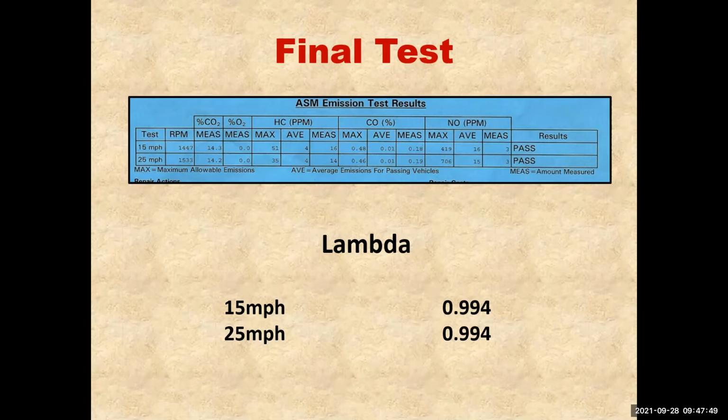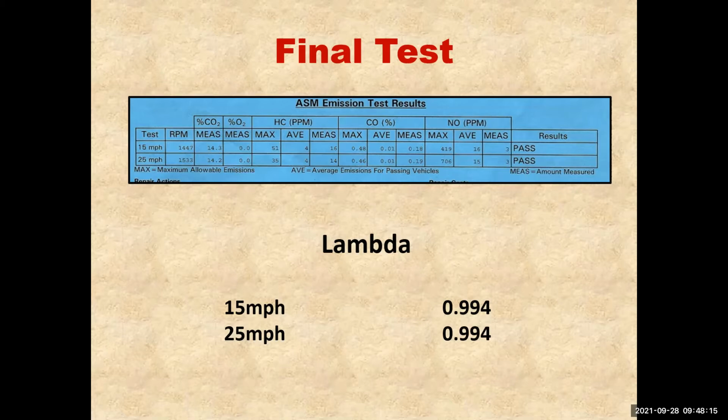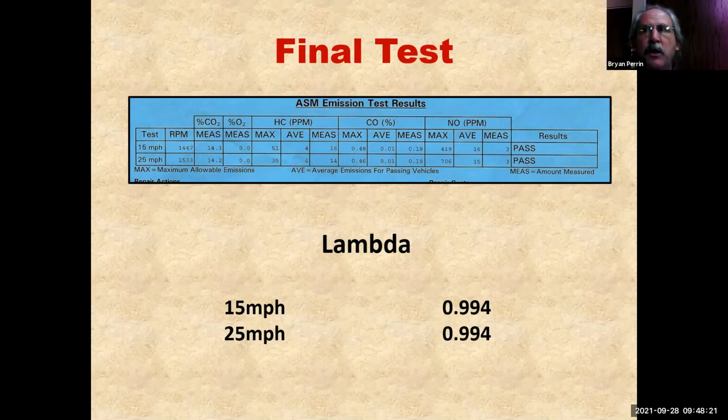And so, go ahead. So driving the car without erasing the code and putting in the new sensor, that was so that it can relearn and give you new values. Right. And the other thing it did, because this was a failed smog, the monitors have to be complete for smog. I didn't want to spend an hour or 2 driving the car to get the monitors complete. So since I'm a lazy flat rater and I get paid by the job I do, not by how long it takes me, and I know the rules are that we don't fail the car for the codes in Mode 3. We fail it if the check engine light's on. I knew the car would pass the OBD2 inspection portion of the test. All I care about is the tailpipe emission.